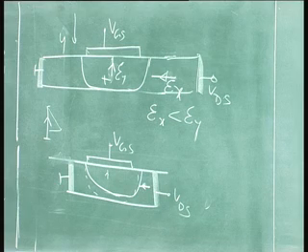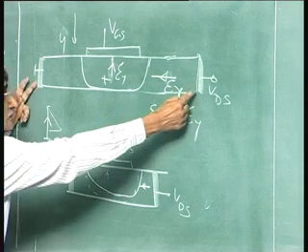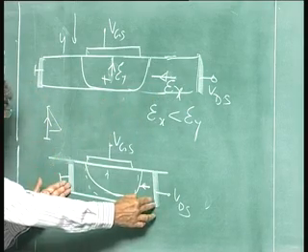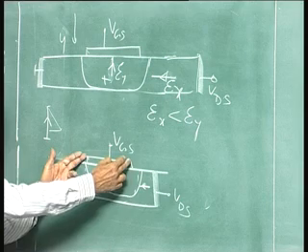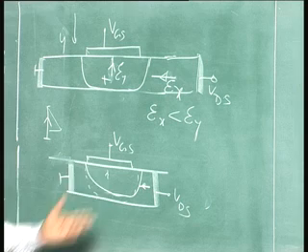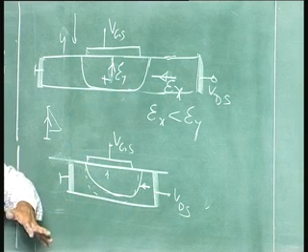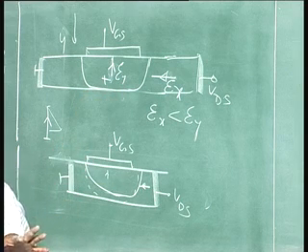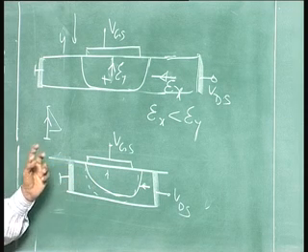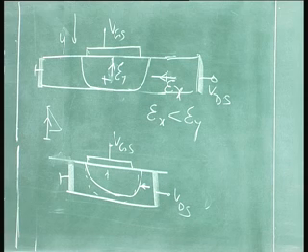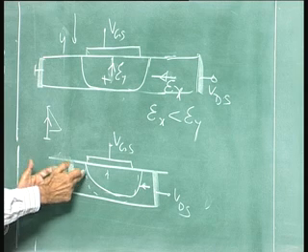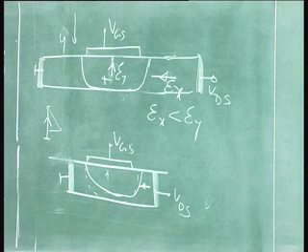So, what is the difference between the two cases? Here the channel length is long, for a given voltage there is a certain field in the x direction. Here the channel length is small for the same gate length, so the fields are larger here. So, two dimensional effects come much more here compared to that. So, the entire depletion layer gets dragged down in one direction. So, it takes more voltage here to close down the channel. That means the threshold voltage is larger negatively. The difference is the gap here is more, the gap here is less. The gap is less, so fields are more along the channel.